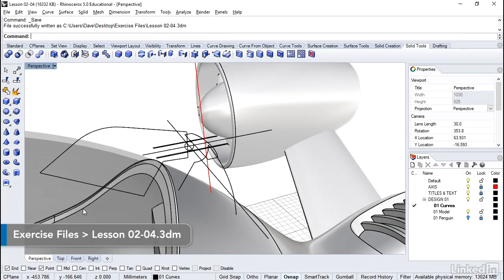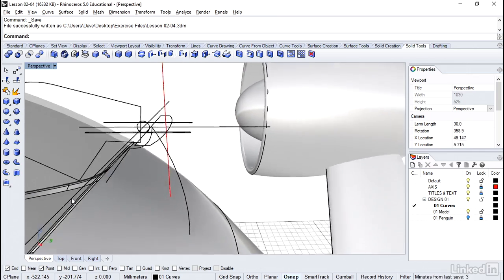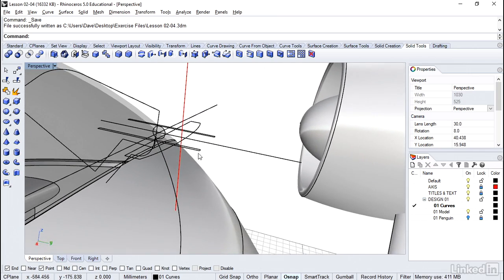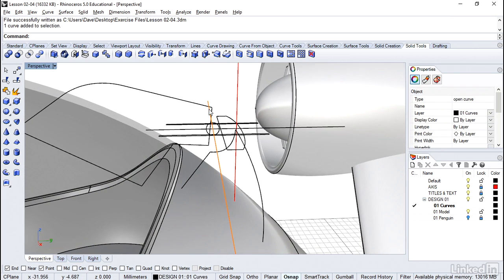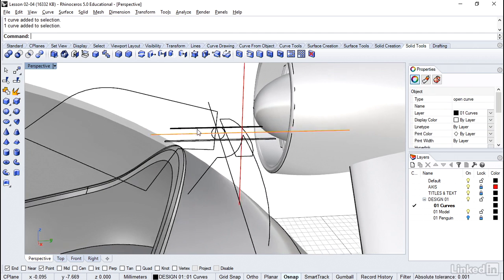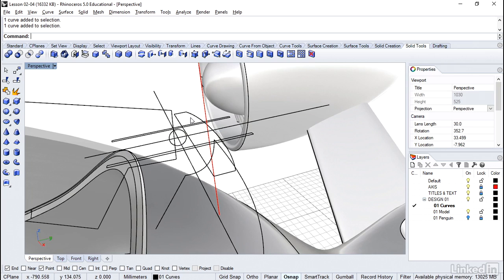So let's go ahead and build our crazy complicated hinge, but along the way you'll see how it's actually not that hard. So I've got all the curves drawn here. Probably the most important thing you can do first is to draw an axis line. We're going to be moving and building geometry and mirroring. So the pivot line is important, as is another center line going down the other way for any mirror operations. Another cool trick I'm doing here is I've got the pin in the center.